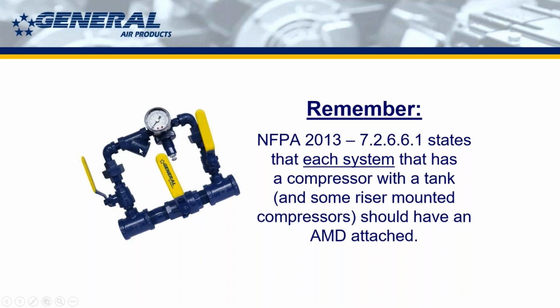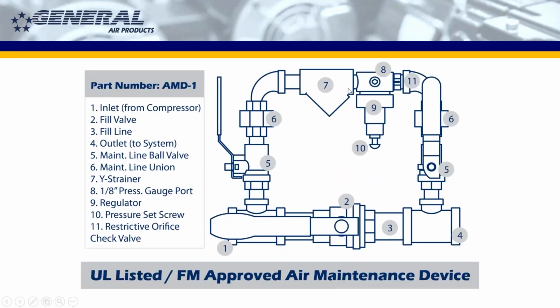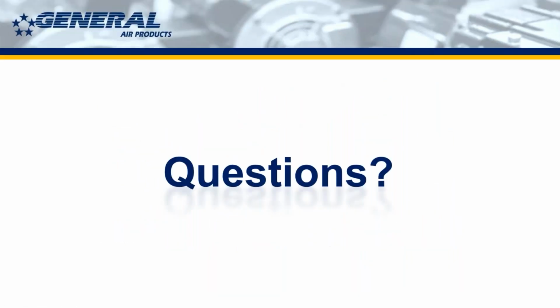But if you were to flip this upside down, it would no longer collect that particulate and those bits and pieces of things that get blown into it, because it will be out of the way. So if you have to install this upside down, what you need to do is put a wrench on that Y strainer and turn it upside down so that the trap is in line with gravity, having the parts drop into it. So another kind of tip there.